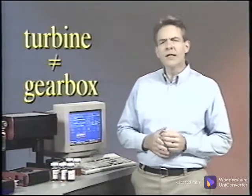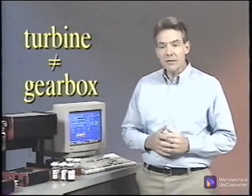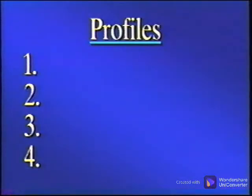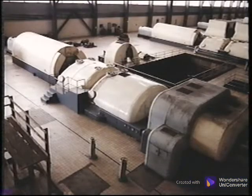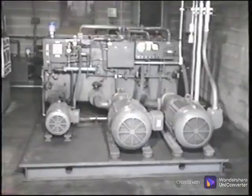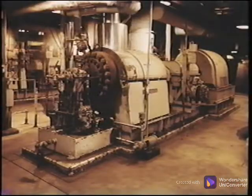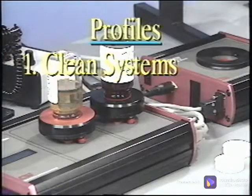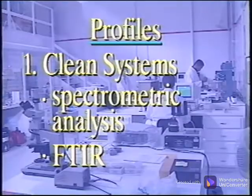A turbine, for example, does not have the same lube requirements as a gearbox and should not have the same tests. There are many profiles, but they can be grouped into 4 basic profiles. One is a clean systems profile, which includes turbines, hydraulic systems, machines with sleeve bearings, and extremely critical contamination-sensitive systems. On-site analysis for clean systems should include viscosity, degradation, and particle counting.